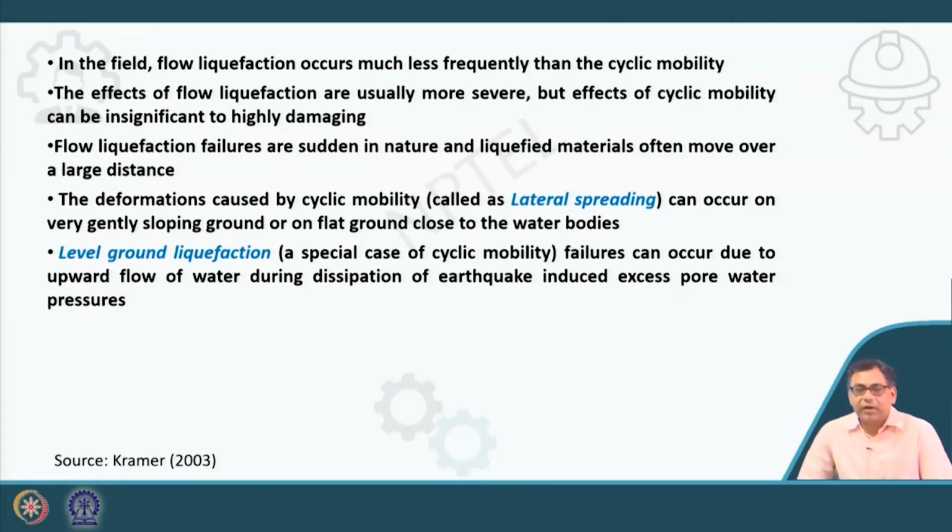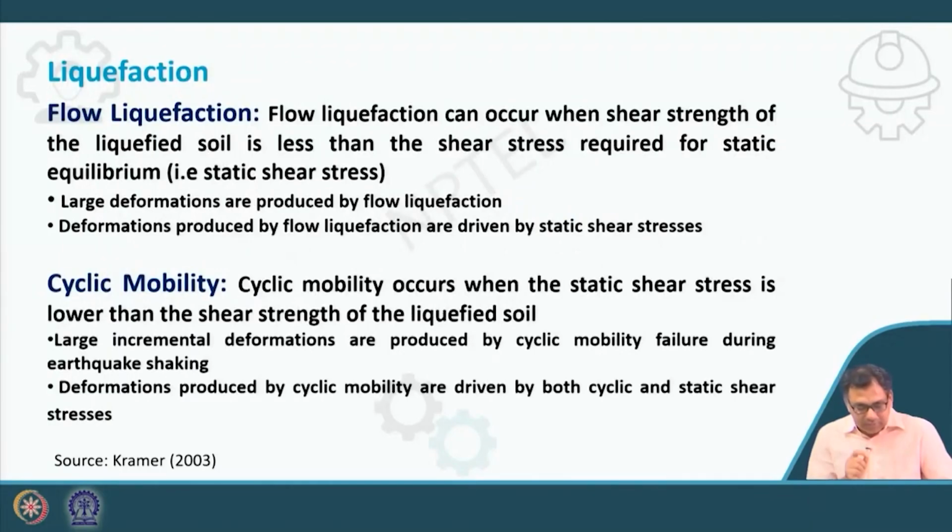But in cyclic mobility, the static shear stress of the soil is less than the strength of the liquefied soil, and the deformation produced by cyclic mobility is driven by both cyclic as well as static shear stress.